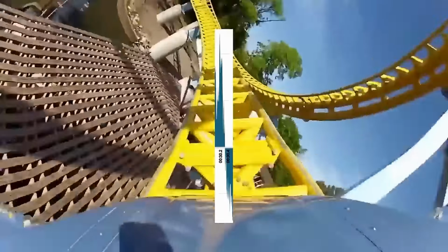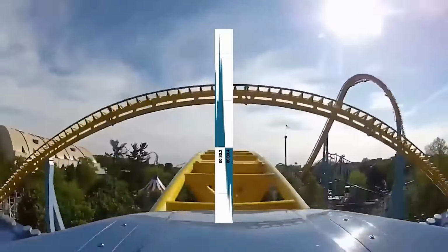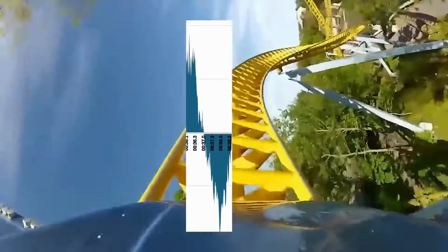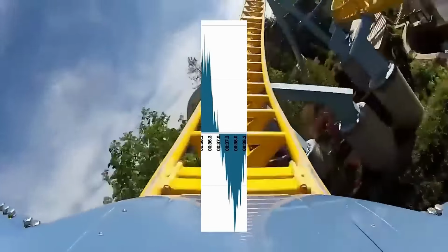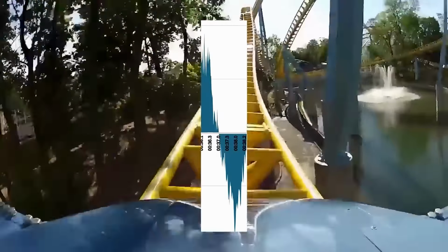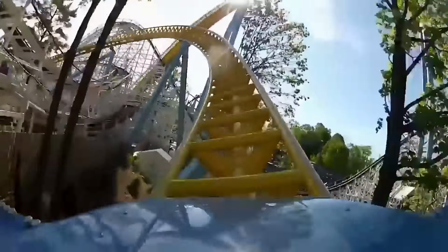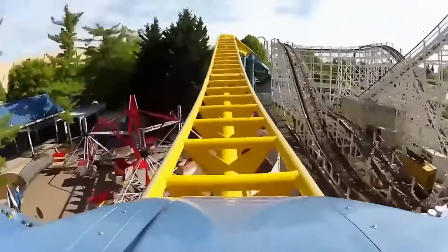Here, entering the third negative z moment on the ride, we can see a textbook 200 millisecond transition from around +3 to 0g. Entering the fourth negative z moment, we can see a very fast transition from positive z forces to negative. Here we can see the designers opted to keep forces lower temporarily during the transition time before riders experience the stronger forces later on in the element. So yes, even a ride as intense as Skyrush is ASTM compliant, and its designers likely worked hard to ensure that it was compliant.